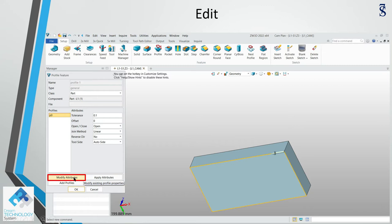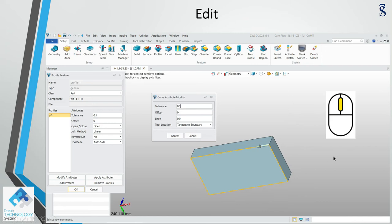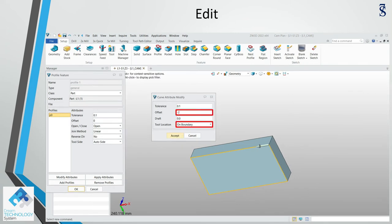And we have to use the modify attribute by clicking line 1 and line 2. So of course there will be a color change, and then you can see that you already picked 2 on the right hand bottom. You can see that there is a 2 pick. Then after that, you click the middle mouse and change the attribute to offset -2. Offset -2 means we travel 2 mm across the part, so that we no need to travel all the way, clear the tool, and then we change the step over.